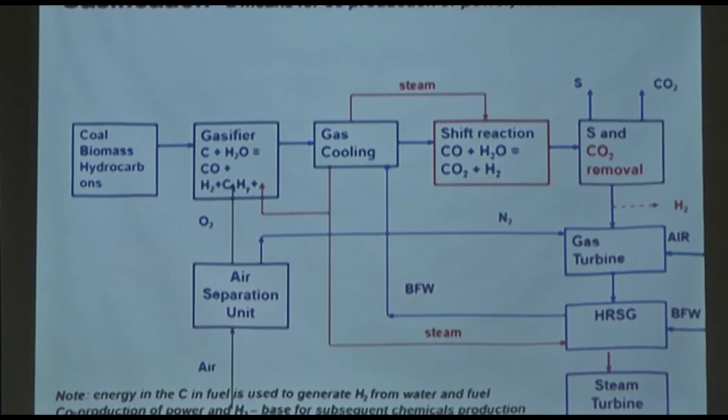The gasifier designs are available, and we will talk about that after lunch. What the gasifier does is that you are giving it less oxygen, but sometimes you also give it steam, not always, and it gives you combustible constituents such as carbon monoxide and hydrogen.